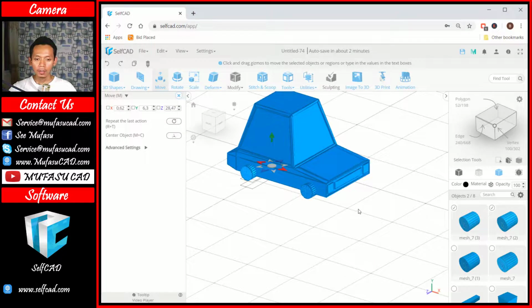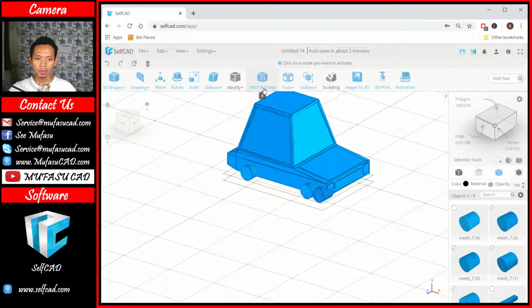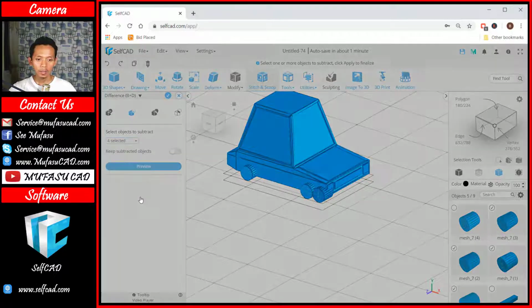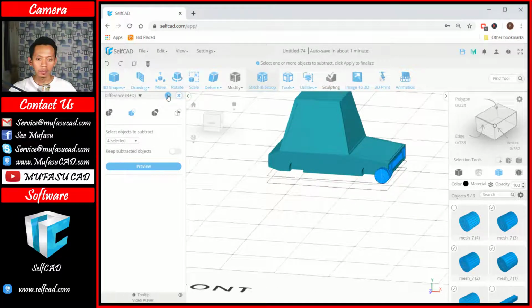I will select all these objects, but first I will copy them. We can use the copy tool, okay, to copy, and then I will select these four cylinder objects plus these objects. You can use Stitch and Scoop, and here I will use Difference to subtract with this mesh tool. Click here, and it will correctly subtract the object in this position. You can click OK to apply.